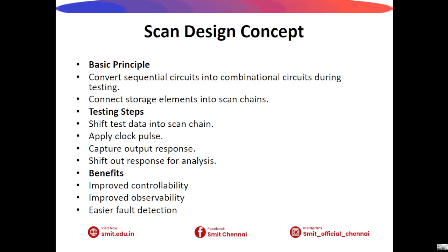Next we see about the scan design concept. The scan design concept forms the foundation of many testing techniques. In normal operation, a circuit behaves as a sequential design. During testing, scan chains allow us to treat the circuit as a combinational system. Test patterns are shifted into the scan chain, responses are captured, and results are shifted out for analysis. This greatly simplifies testing and improves fault detection.